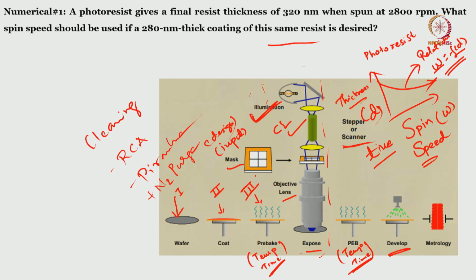So, light will get diffracted and it will pass through some portions and get diffracted at edges, and then based on this objective lens and diffraction and several other known optical events, you will get it here. But when you get it here, that particular portion of your wafer where PR is there will have a slightly different chemical property and will behave differently during development.